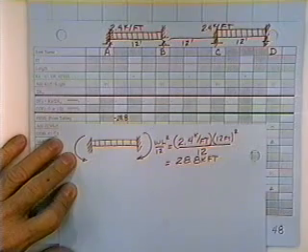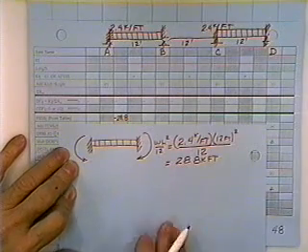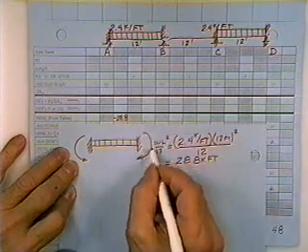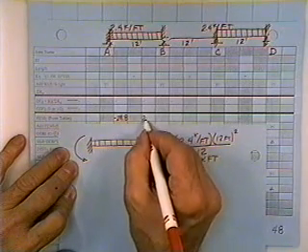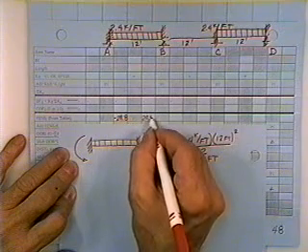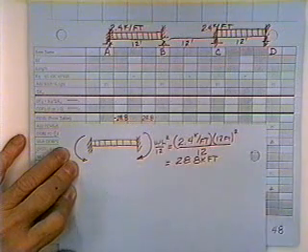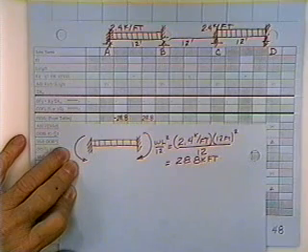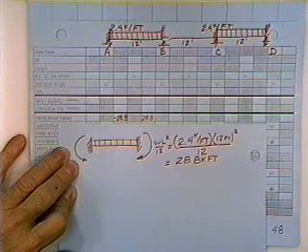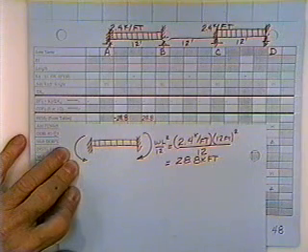It should be loose. On the right-hand end, since the moment is clockwise, I'm going to enter a positive 28.8 for how much torque, how much moment a guy with a torque wrench would have to apply to the end of the joint in order to get the beam fixed on the right-hand end.